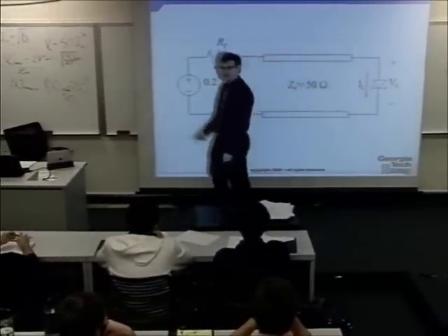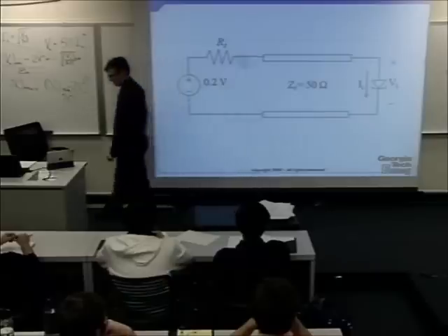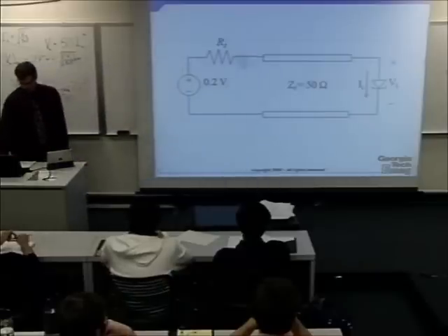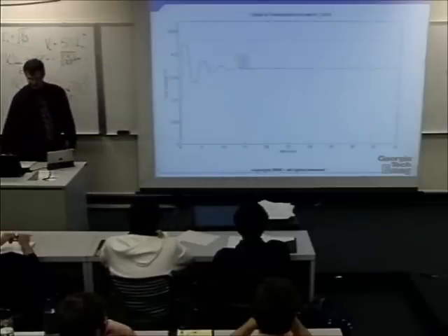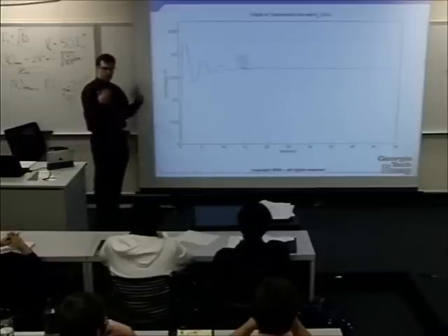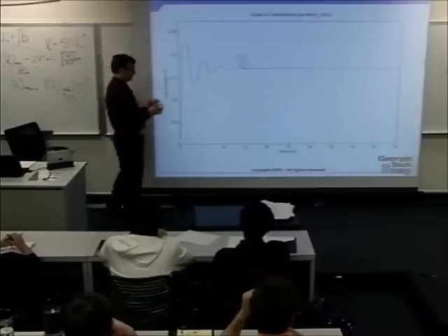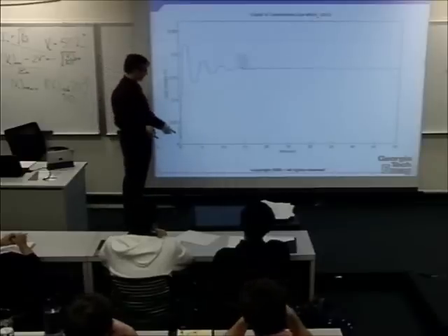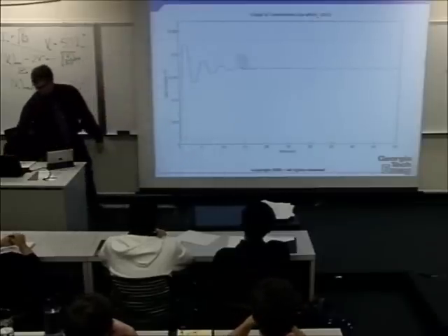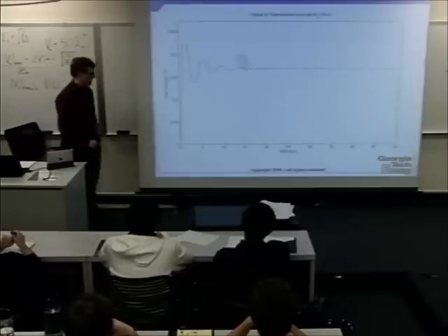And we're going to use that iteration technique. I'm going to do it on the computer, not on the board, so that I do not belabor the point. And here's an example when R sub s is equal to 20. And you can see I can use the iteration. This is what computers are good for, right? Solving iterative equations and then doing it for each transit time. I believe my transit time in this circuit is about, I don't have it listed, but it's like 1 nanosecond.